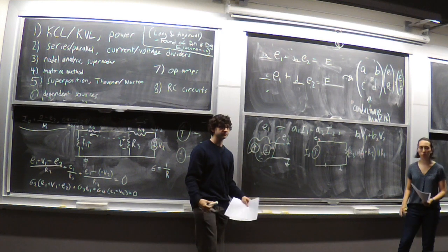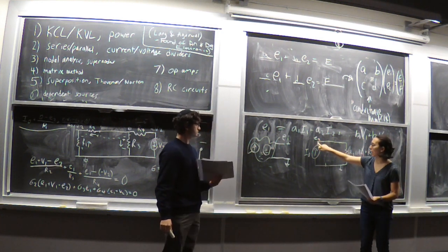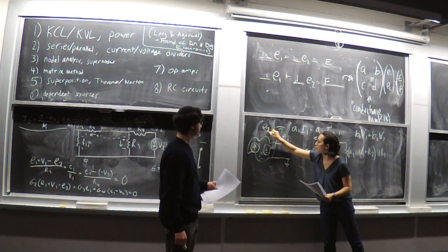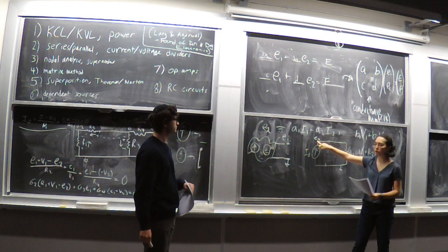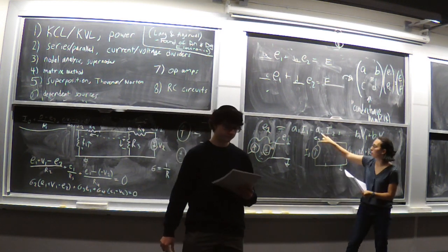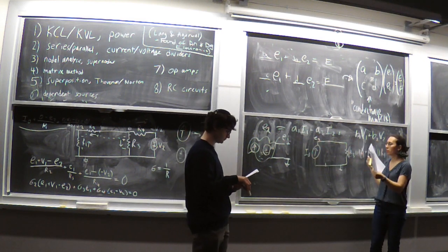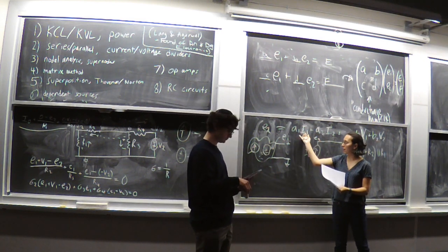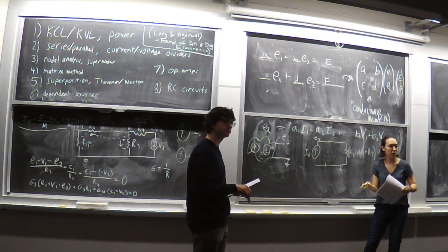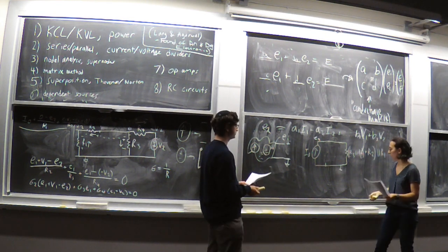So when we're turning off sources, what we're computing is not actually the full E2. Let's say that's E2. We're not computing the full E2 when we look at the partial circuit. What we've computed is some partial term, something on the right-hand side, and we found the contribution that term has to the full E2. Does that make sense? So that's why you can add these circuits together.